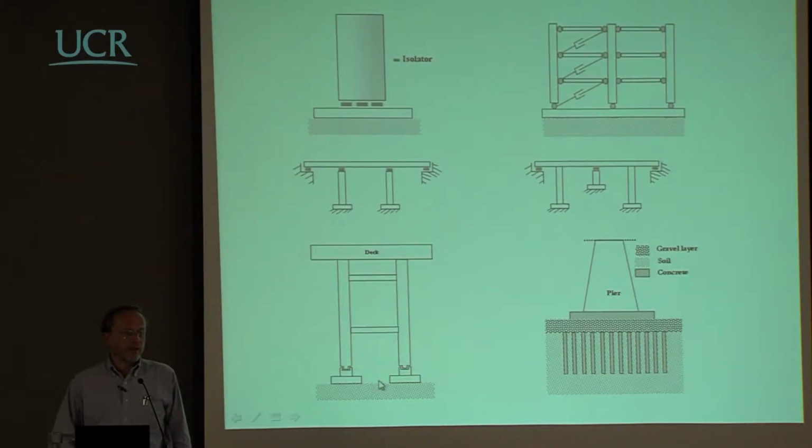A rocking bridge pier is essentially an isolated pier, because when you have the possibility for one leg of a frame pier to raise up, it means that the shear force cannot increase anymore, actually should decrease, unless there is some tensile capacity at that level. So this is another very interesting kind of isolation system that could be used for bridges, but could be used also for other structures when you accept to have some rocking behavior of the whole structure or of part of it.